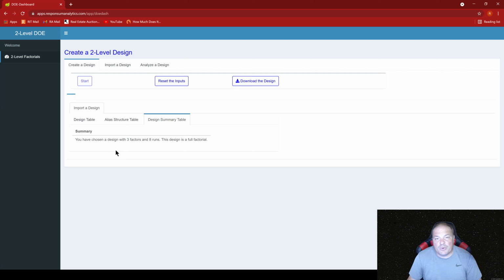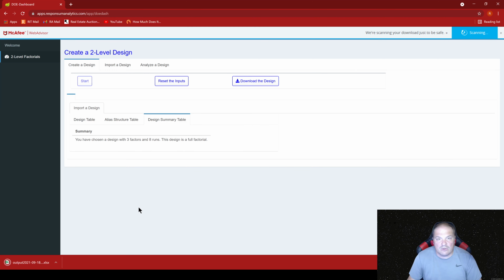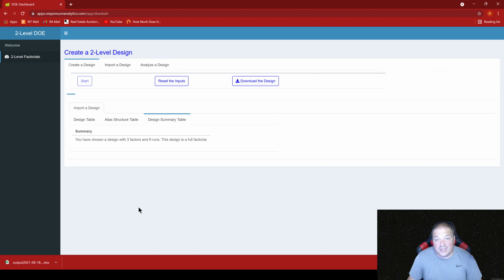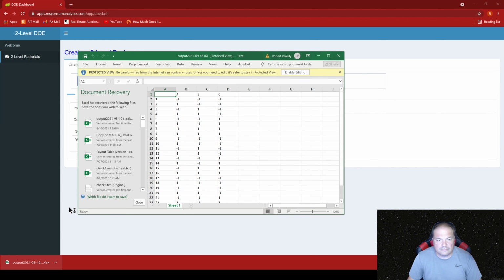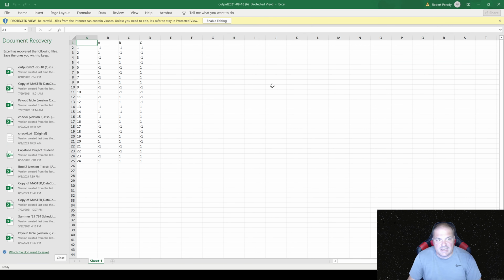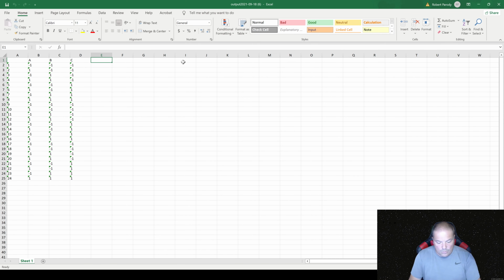Okay, so at this point, what we're going to want to do is download the design so we can load in the responses. So we're going to click the download the design button. And what that's going to do is it's going to download and create an Excel file with your design in it. So let's click on this. Okay, and you can see here that here's our A, B, C columns. They match what we saw. What we're going to do is we're going to add a column for Y after I enable editing here. Okay, where Y is our response.